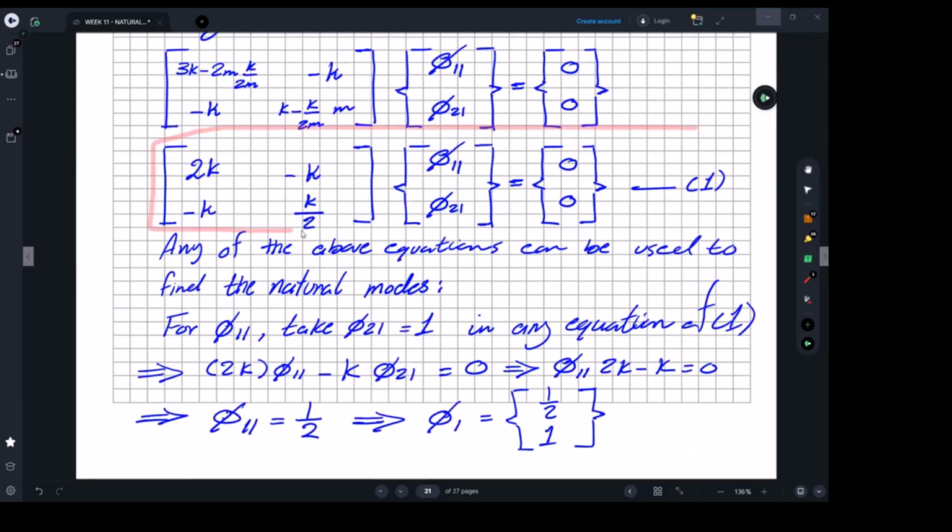Now, we ended up with this double coupled matrix equation. Remember our aim is to find the value of the mode shapes. The way to find it is we have to assume one of the phi's to be a scale of 1 or 100%, whichever some textbooks use. So for the second floor mode shape 1, we're assuming the phi is going to be 100% or 1.